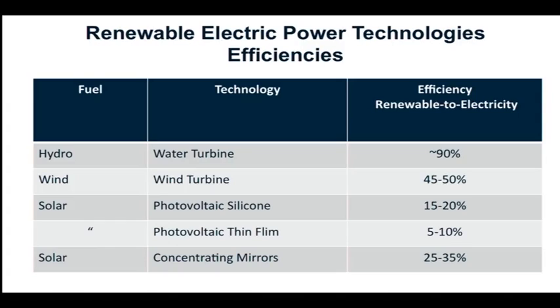The silicon chips, thin wafers, polycrystalline, will get 15 to 20% at the peak radiation efficiency at noon, typically, and convert it into electricity. So that's 15 to 20% of all the sun's energy that's falling on the module, the collector module, the PV module, will be converted to electricity under the best conditions.